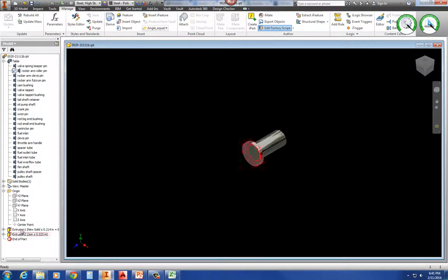Okay, I got that. So I need to name these. I'm going to call this shaft, and I'm going to call this flange, because if I'm going to either compute or suppress something, I have to have a name on it, or I'm not going to know what it is. So shaft, I know kind of what that is. Let's get to the next point. We have some chamfers on both ends. So we're either going to compute or suppress those, right? And if we have this flange, it has to have the chamfer on the flange, or it won't compute. It can't formulate that.